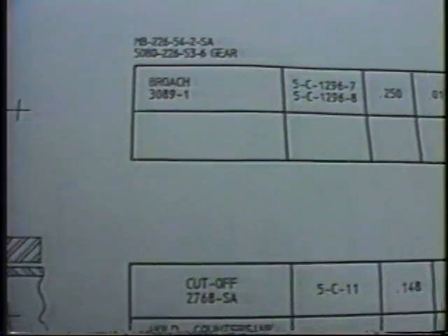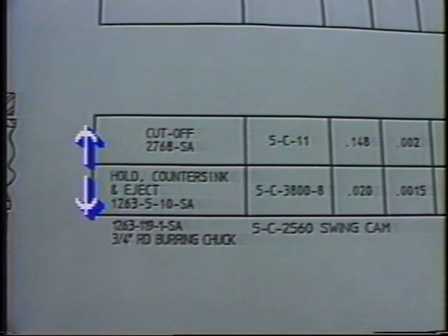End-working operations are contained in the top block and side-working in the bottom. Required tool holders, spindles, and idler arrangements will be identified either in this block or directly above or below it. It should be noted that in the 5th position, the cross-working and end-working operations are reversed. That is, the cross-working operations are listed in the top box and the end working in the bottom.